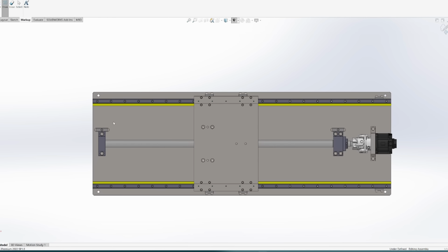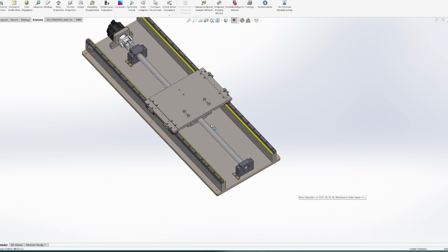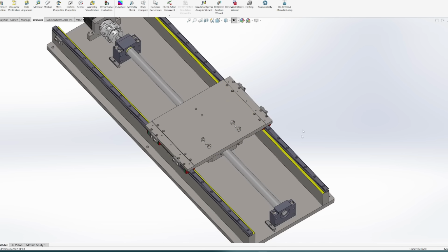And this makes the user or customer deeply disappointed. So a better solution is to add a simple locating feature, like a key on one side of each block. So every time you assemble, alignment is already defined, no trial and error.